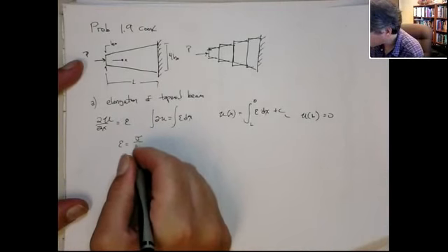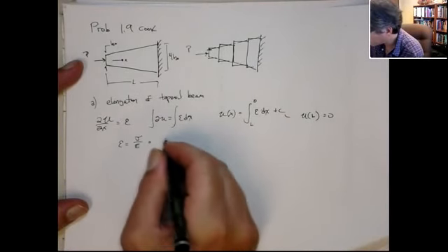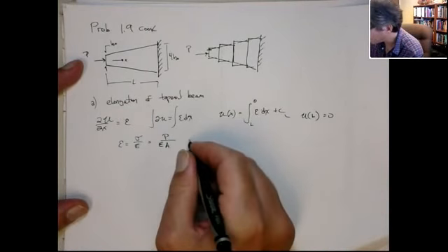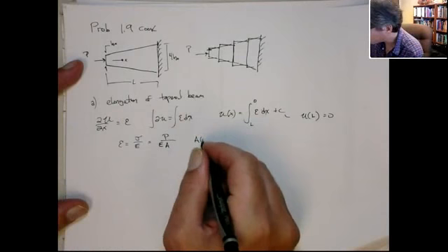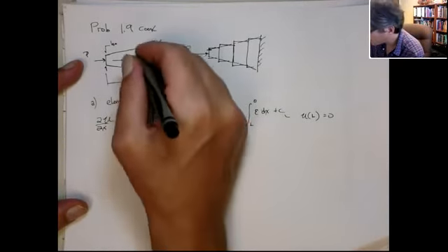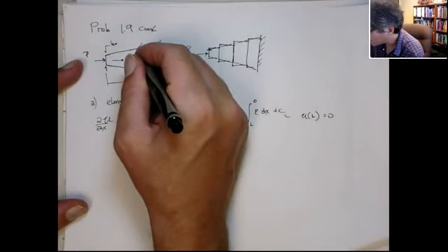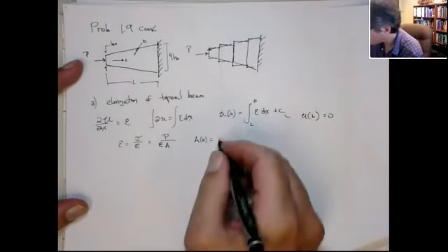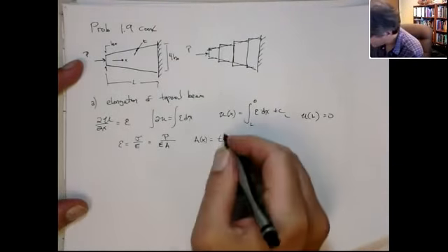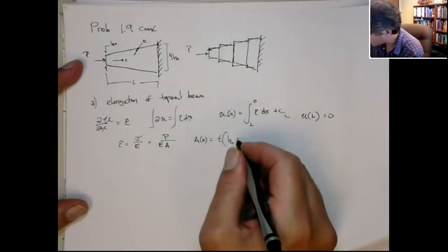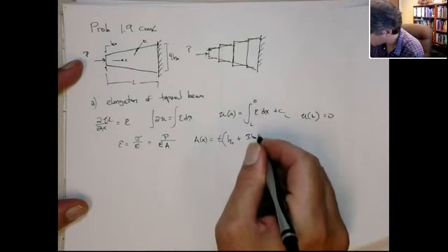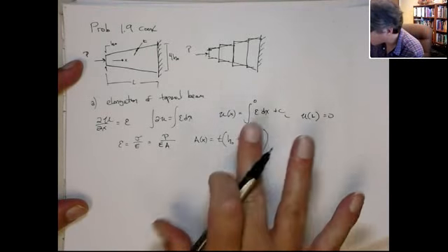Okay, so the strain is the stress over Young's modulus, and then the stress is the force over the area, and the area is a function of x. Cross-sectional area changes, and it tells you that this has a thickness here of t, so the area is t times the height. The expression for the height starts at h0, and then it goes to 4h0 at x equal to L, so we do 3h0 x on L. If you put x equals 0, you get h0.